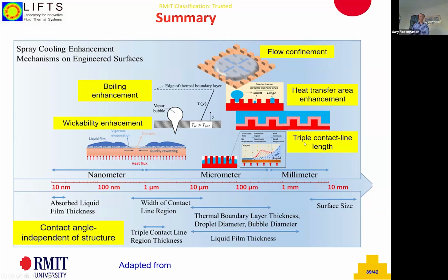That triple contact line length, I haven't talked about it much, but I think there might have been other talks in that field at this workshop. And the contact angle. The contact angle changes the fluid dynamics, no matter what structure, no matter the size of the underlying structure of the surface. So that summarises that. That's an incredibly important one.